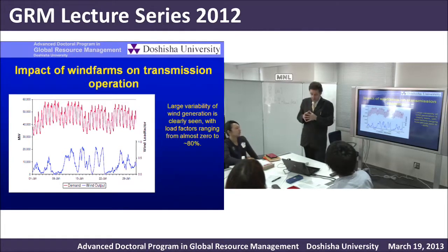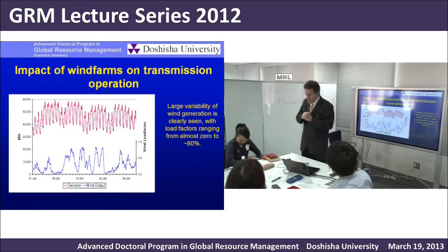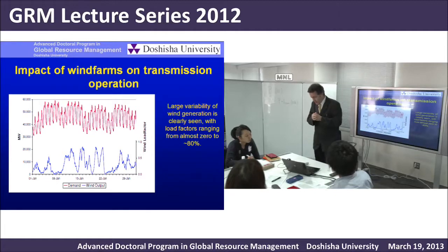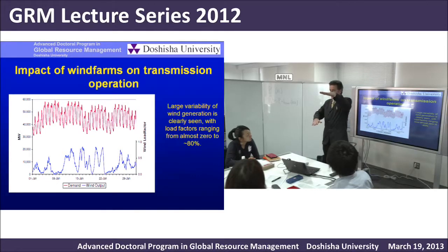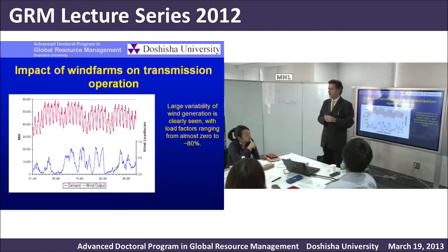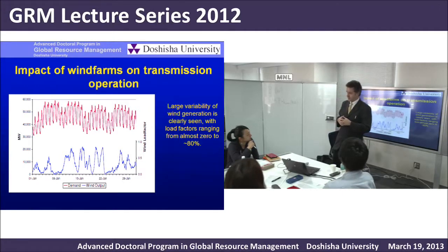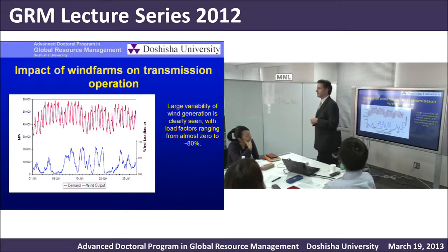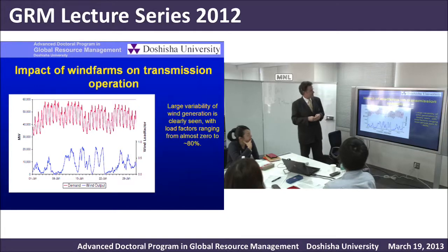The most effective methods of storage, and we have such schemes, we've got a 2 gigawatt pumped storage scheme. Now what that means, we've got 2 lakes very close to each other, and we've got a generating station which can pump water from the lower lake to the upper lake and store the potential energy in the upper lake and then release it. So it's a little bit like digging a hole in the ground and filling it back in again. It seems like a pointless exercise on one level, but on another level it makes incredible sense because you can store electricity when you have surplus and you can use it when you have deficit. And the efficiencies are around about 80%, 80-85%, so it makes sense.